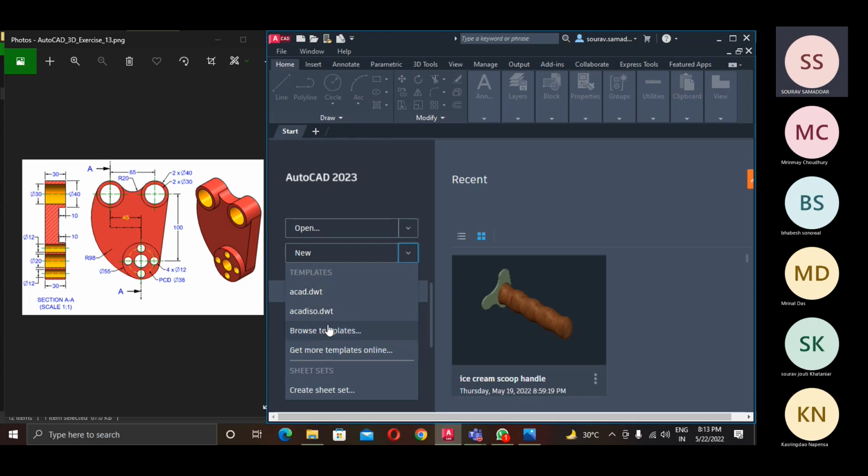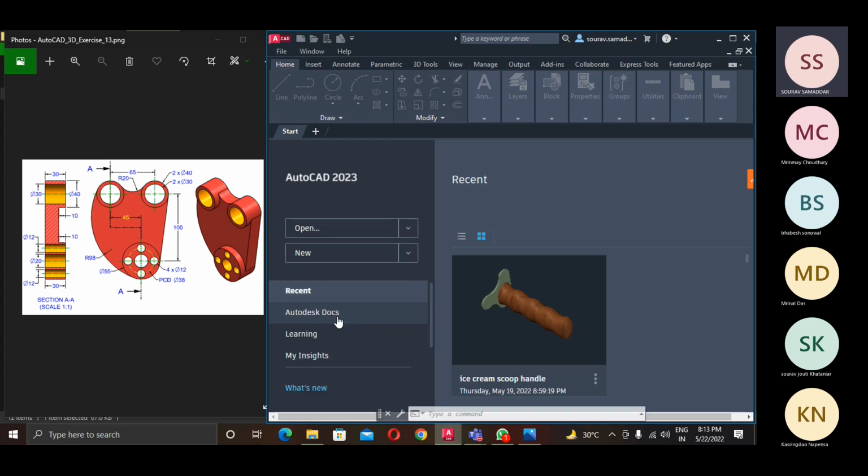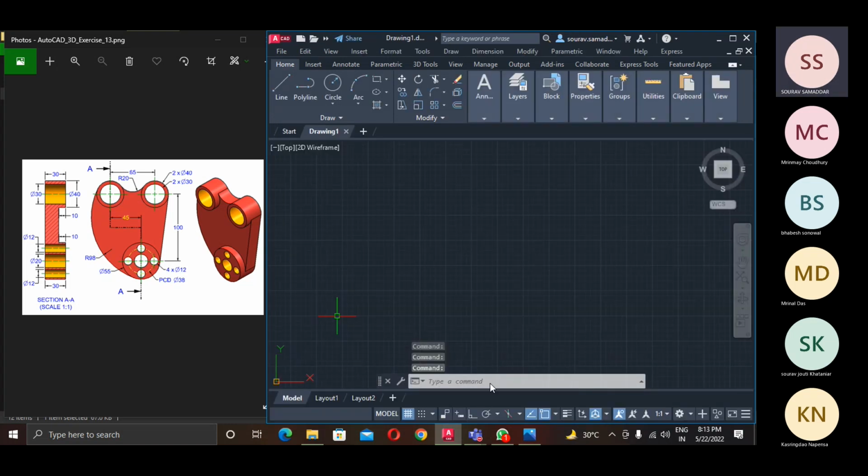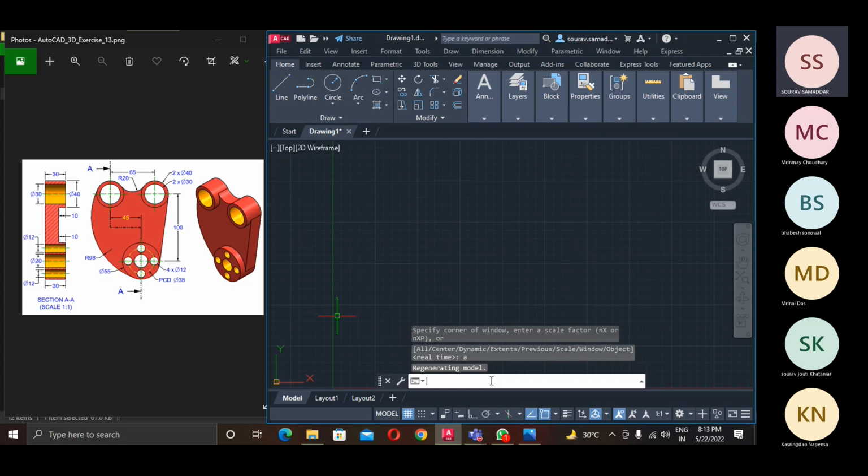So the maximum dimension in this drawing that is right now showing 100. So choose the ACAD ISO option and then go for zoom enter all enter, that is Z enter and A enter, and then start your drawing. In case you have to convert your 2D drawing into a three-dimensional drawing, you don't need to apply those kinds of dimensions and center lines. Those are only for 2D drafting purposes. But make sure that you have entered the correct data, otherwise your drawing will be incorrect.